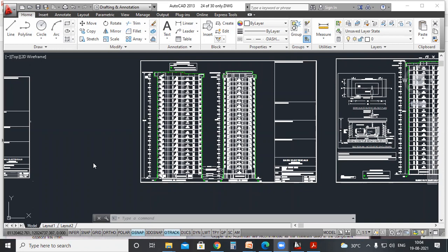Calculation means you're just following the standards and there are some values. For example, according to the location, we have to take some thunderstorm days value given in the standard, and based on that we have to check, along with the building height, length and width, whether lightning protection is required or not.